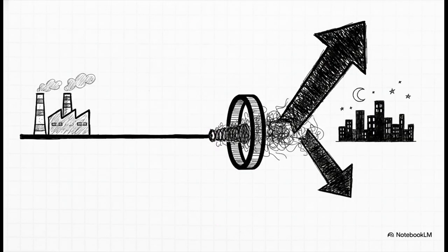The culprit behind this 2 a.m. spike is something called the Ferranti effect. Here's what's going on. A lightly loaded long line is essentially operating below its surge impedance loading point. Because there is very little load current flowing through the line's inductance, the line starts acting like a giant capacitor. It generates way more reactive power from its shunt capacitance than it consumes, which physically pushes the voltage up at the far end. The standard industry fix? You switch in shunt reactors to absorb that excess reactive power and literally pull the voltage back down to safe levels.